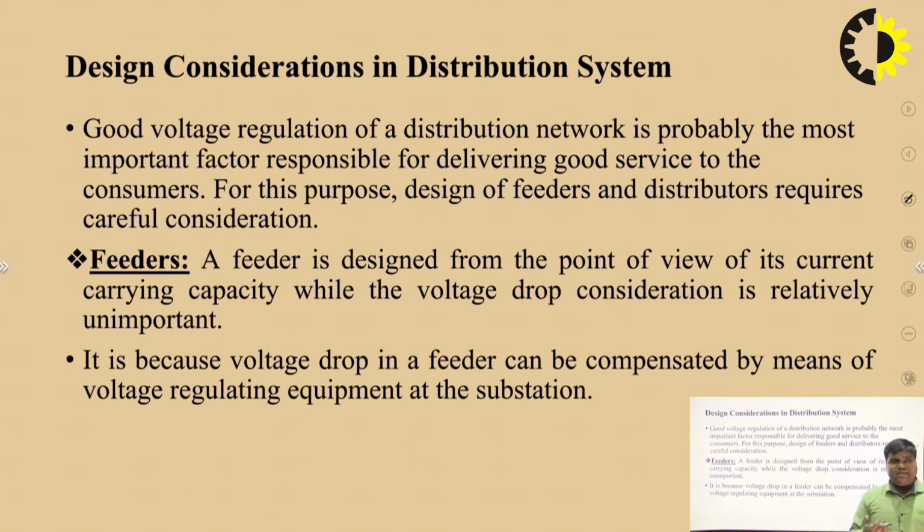So listen to me very carefully. What is a feeder? A feeder is designed from the point of view of its current carrying capacity, while the voltage drop consideration is relatively unimportant. In the feeder, the current carrying capacity is high, and the current is almost uniform in the feeder side.